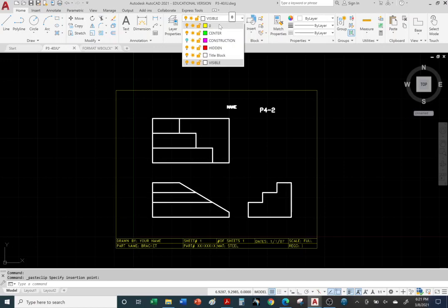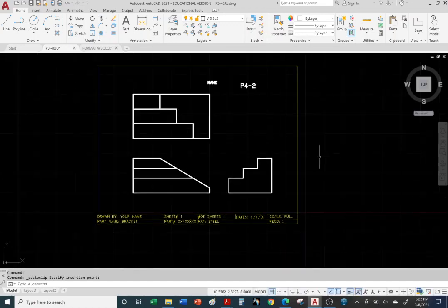So if you open up a new drawing from scratch, it has to have a layer, right? So you can start drawing. If you're not aware about layers, you're going to try and draw, but if there's no layers, then you won't be able to see your lines. So there has to be a layer, and that's the default that comes with AutoCAD. Default layer 0. Okay, so that's one option. You can use this title block and border if you like.